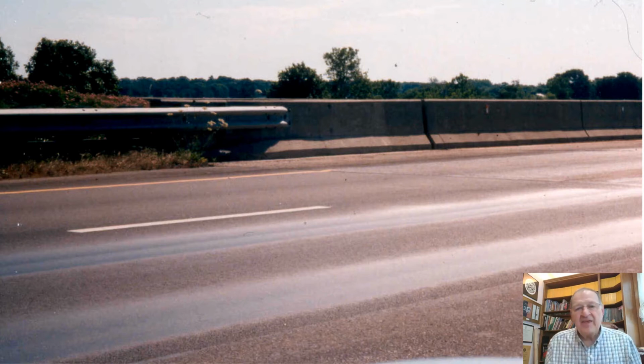But in the areas adjacent to some overhead structures, they not only milled and replaced the surface, but for a couple hundred feet before each bridge, they did the intermediate layer as well. And there you can see that there's actual rutting that is taking place, not only the bleeding, but the rutting.